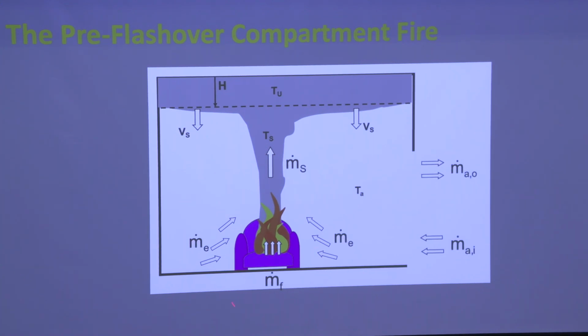So you ignore entirely the production of fuel. You ignore the fluid mechanics that brings air and brings it out, assuming it just simply happens. You ignore all the flow field in the cold area, and effectively all you do is, by means of a heat release rate or amount of energy produced, some fraction that is lost due to radiation, and some empirical correlation that relates that heat release rate to the entrainment, you can calculate the amount of smoke and the temperature of the smoke that then you input as your only input into the smoke layer, okay?